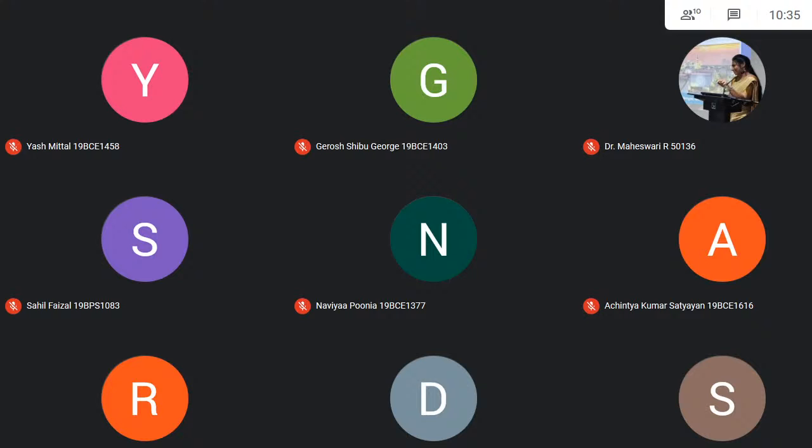So when a delay happens with respect to data, we call it a data hazard. When a delay happens with the dependency of your control instructions, like if, for, while, and all these conditional instructions, we call it a control hazard.